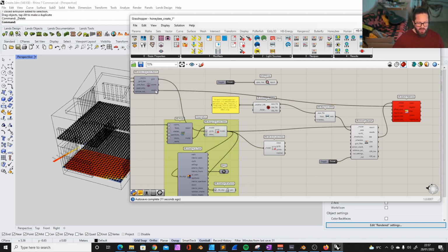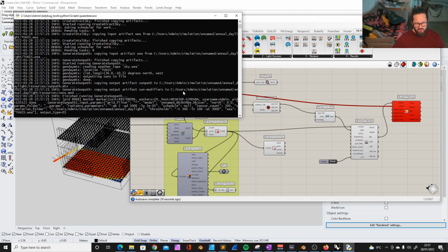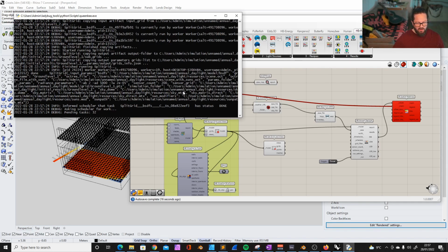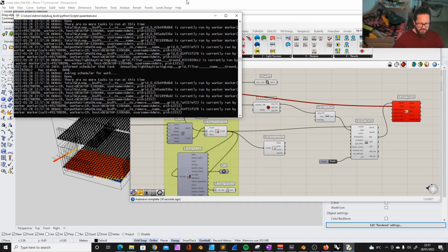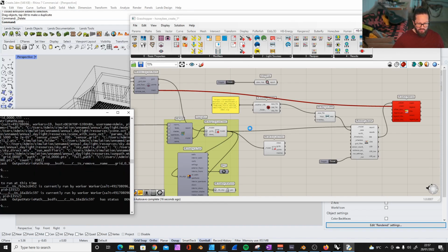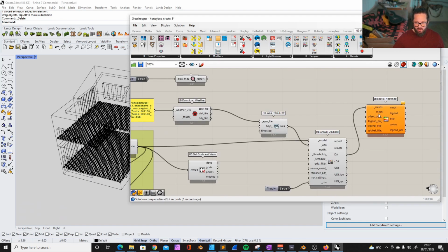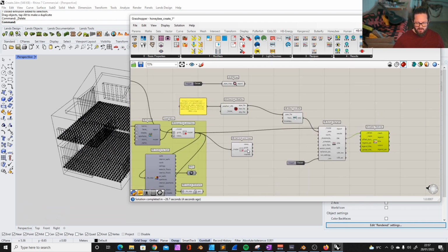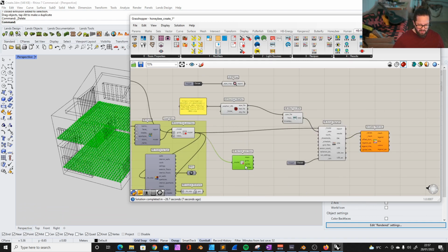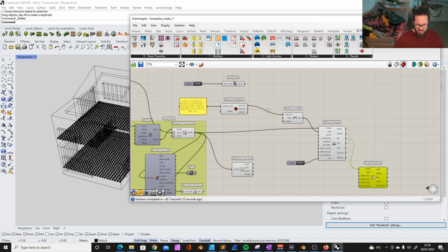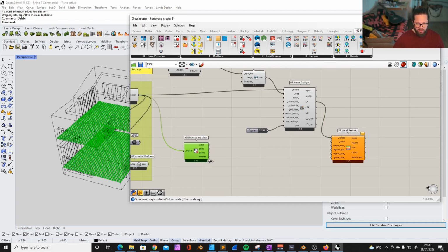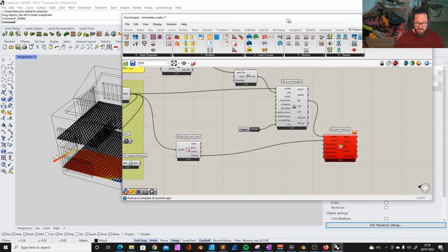If I change the mesh here, it will recalculate everything. So I just disconnect this here. Now it also does that recalculation, because it's going through the model, and whenever we change something in the input here, it will rerun. Now you can't see anything, of course, but if I get the meshes after the model, which then don't have an influence on the input here, then it doesn't rerun. That's very helpful.